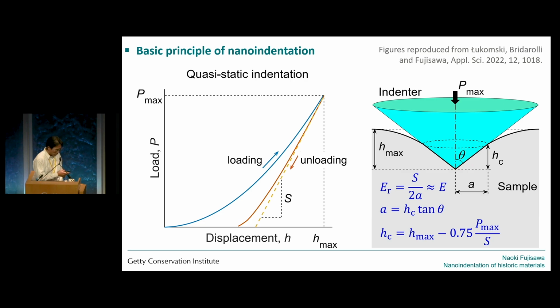And assuming that the unloading response is fully elastic, it determines the elastic stiffness of the sample as the slope of this unloading curve at the beginning.